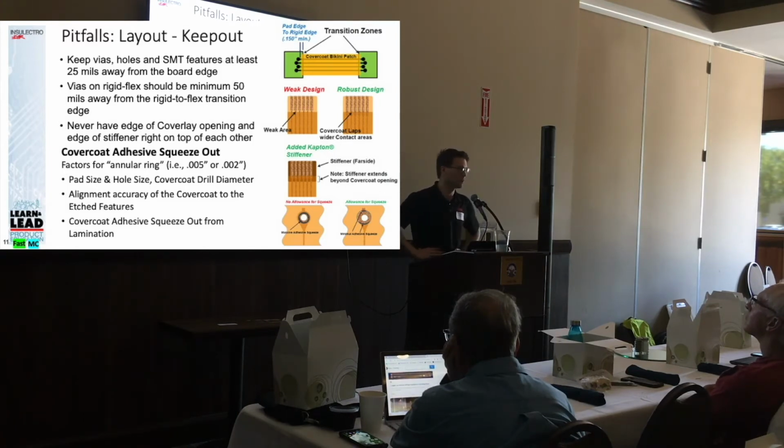But to Jerry's point, when you have acrylic in the rigid section and you go through a thermal expansion event, that acrylic starts to expand significantly faster and earlier than everything else inside of that package. So that is the biggest reason and driver why we do not want acrylic adhesives inside of the rigid board itself. When we have a little transition zone between two rigid panels, we want to pull that cover lay out or the acrylic adhesives outside of the rigid sections.